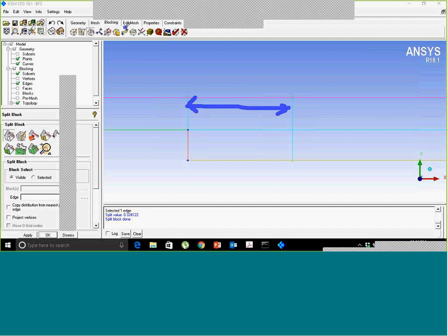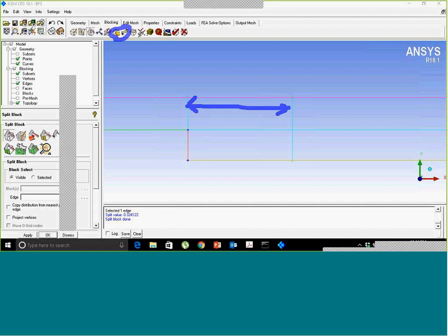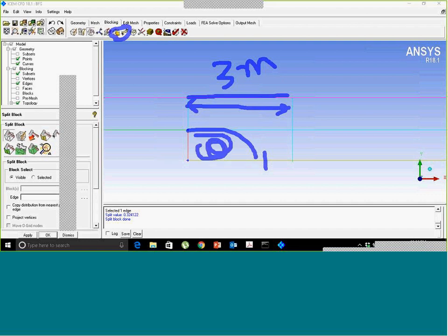So I have the option over here, move vertices. Based on this one, I can exactly set that this length should be equal to 3 meters. With 2.78 I have the saturation zone and region here. I can very nicely capture this saturation zone, and I have very accurately the reattachment point also in my CFD. So this is the way I use the blocking.